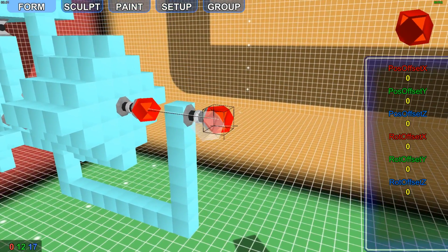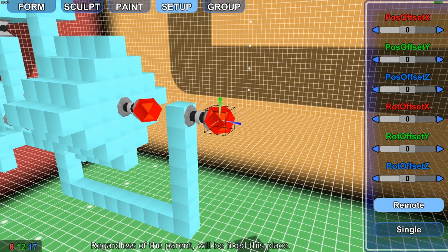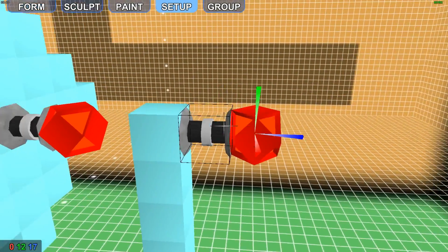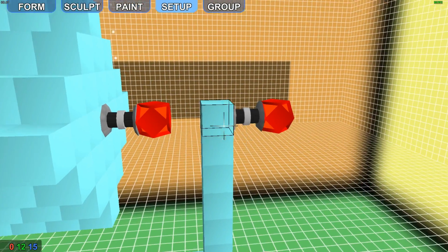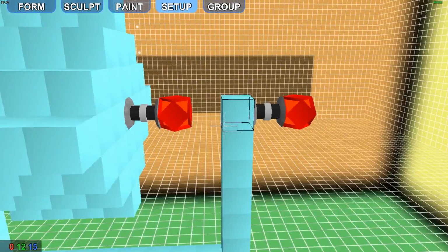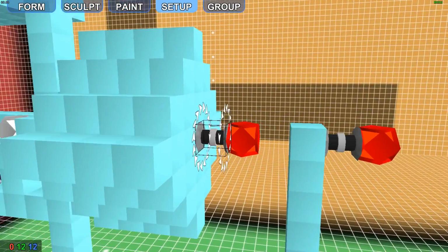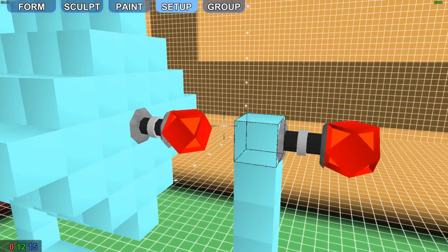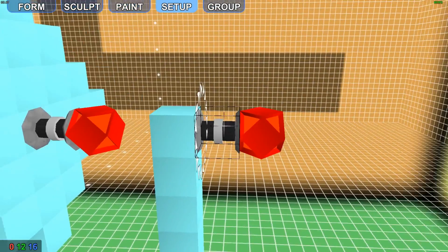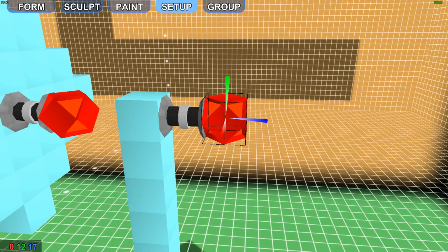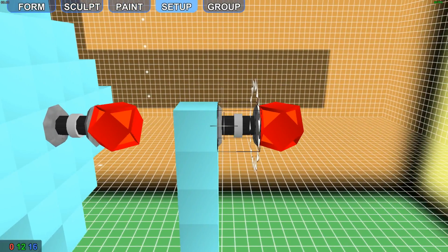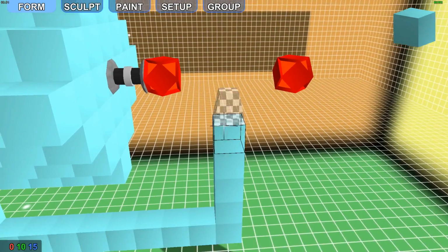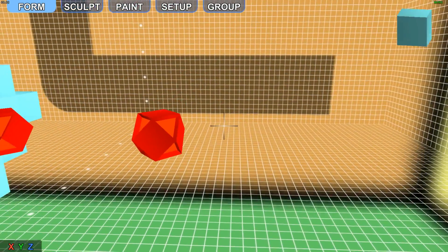Alright, and then this needs to be set to remote, or else it'll snap. If you don't do that, the coupler will, like, this will go to here. So like if I didn't have this whole 2 separate constraints, then this would do some weird stuff, and it would try to join that body, like this go into that, and whatever's connected to it will move to there. I'll just show you an example of what I'm going on about, because it's kind of crazy looking when you see it.